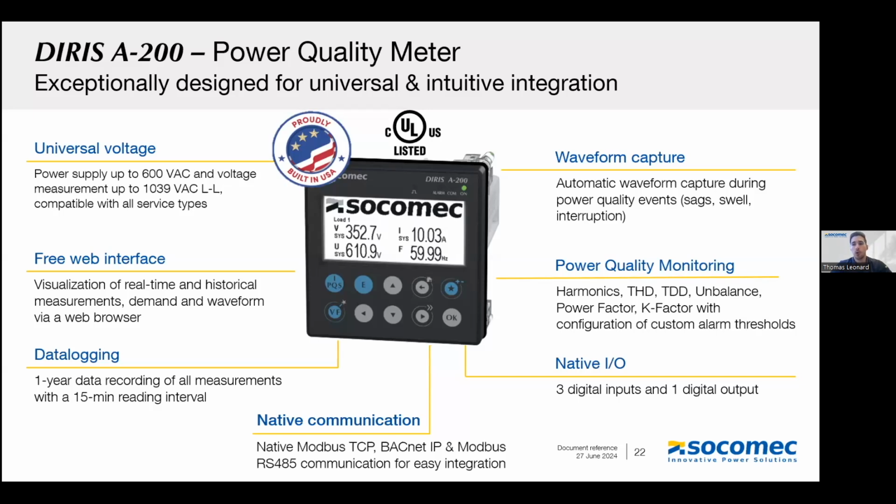The meter comes with power quality monitoring functions. So it'll monitor harmonics, it'll monitor imbalance, power factor, K factor. So it's really a variety of parameters that are well known at this point. All of these parameters are measured and stored internally in the meter. We can actually record a 1-year log of measurements with a 15-minute reading interval. So a data point every 15 minutes will be stored in the meter for a year. You can change the reading interval, you can increase it to 1 hour, and in this case, we'll store the measurements for up to 4 years.